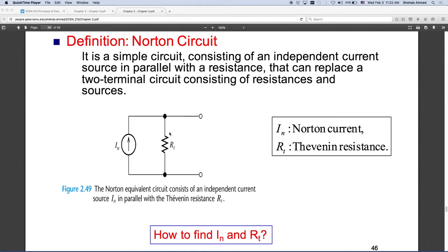Because that box at the end of the day will have some potential difference or voltage across the terminals, and if you put a short circuit, current will flow. If I put a short circuit around this box, what's going to flow? This Norton equivalent current will flow, right? And if I have an open circuit here and I connect something here, this other circuit will affect the current flowing in this resistor, and hence I will have a voltage across, right?